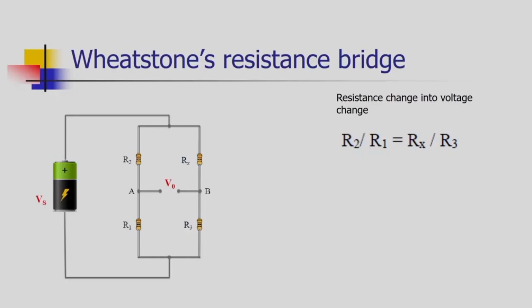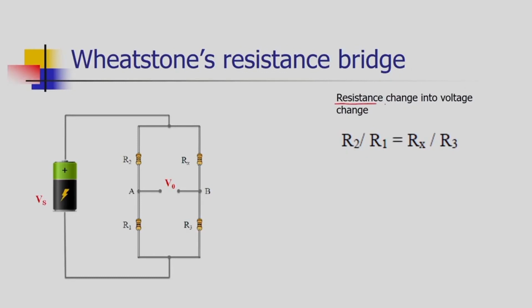Well, the strain gauge element is providing us a passive output. Passive output, as we have seen, is producing the change in resistance. But for microprocessor processing, we need an active element, we need the voltage, a change in voltage, a pulse of voltage, that is the digital signal that is useful for the microprocessor. So, for that purpose we have to convert the resistance change into voltage change. To carry out this operation we are using the Wheatstone resistance bridge.